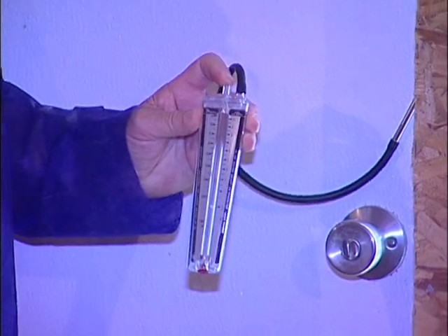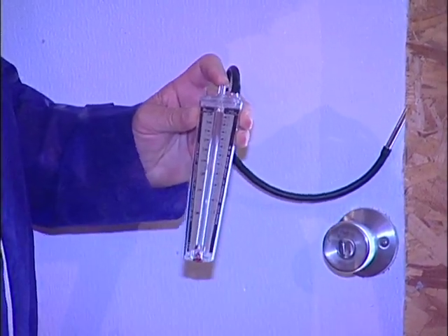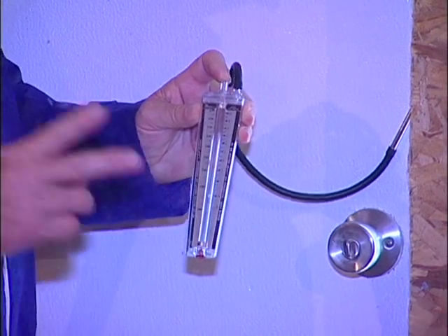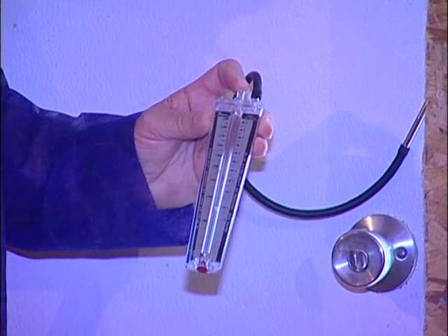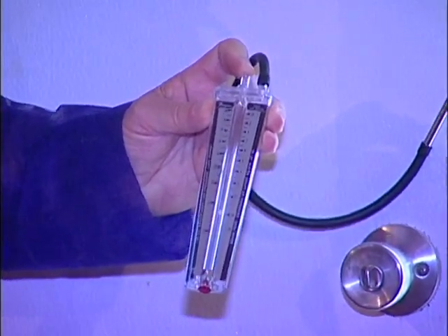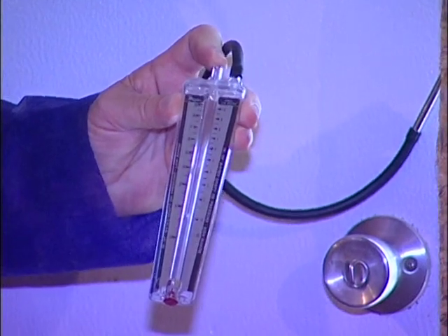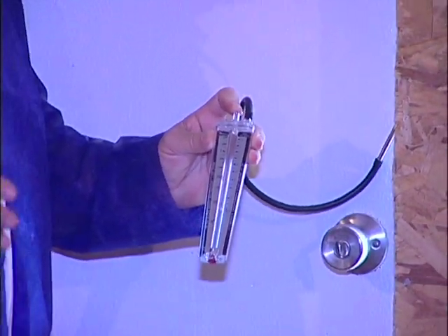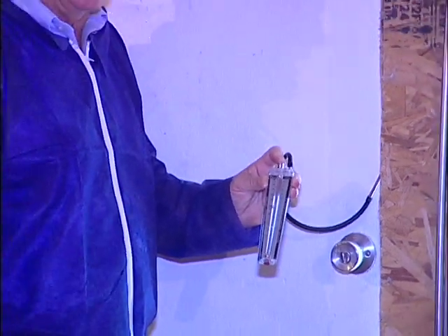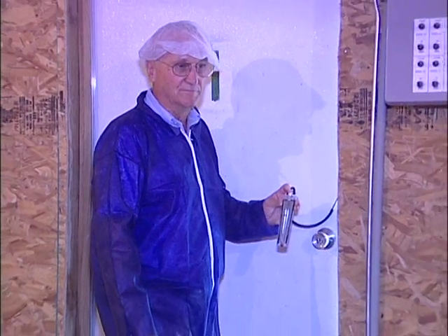So now I come back and stop this up and read the high pressure side of this control. With two fans running and the inlets closed, we're just a little bit above 0.10. In fact, we're almost at 0.125. So that's excellent for a house this size with two 36-inch fans in operation.